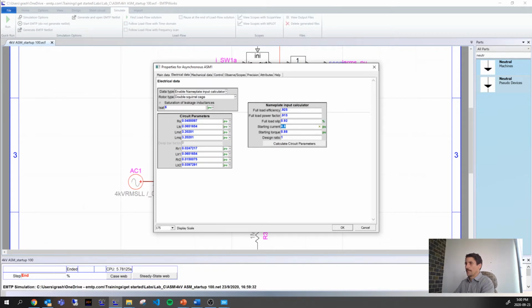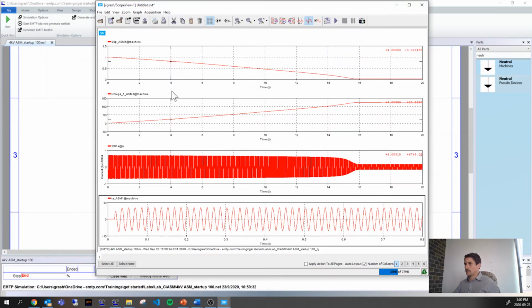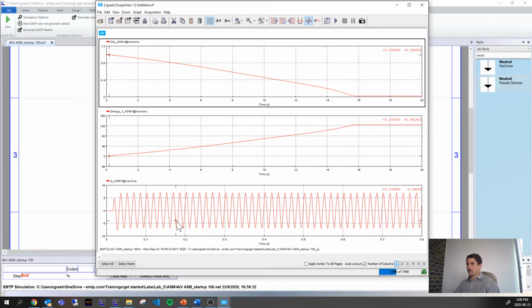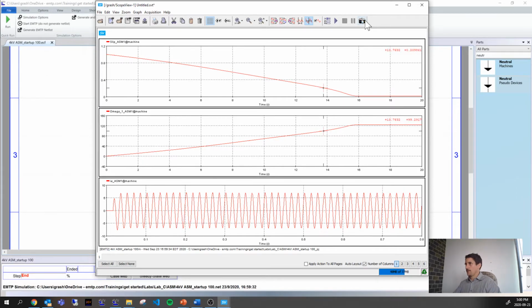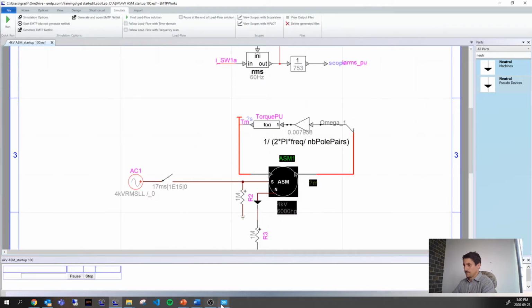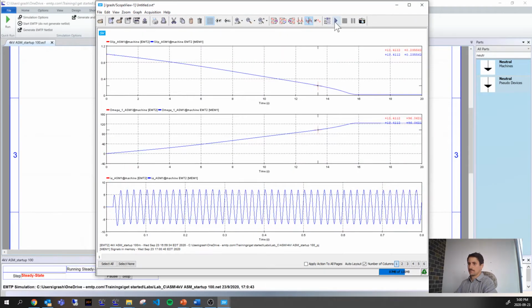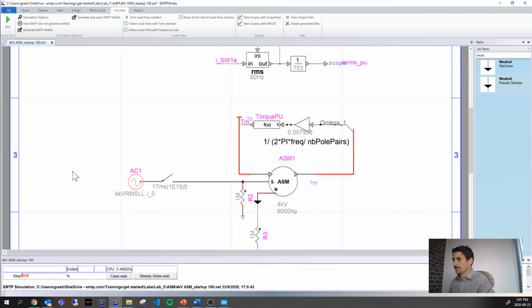Okay, you can check out the influence of this parameter. For example, let me remove it and save the three results that we have here, and run this again. Okay, so you see how it affects the starting time. Now I start later. So you may play with this parameter if you know the starting time of your machine and you want to adjust it to really match, you can use this parameter.